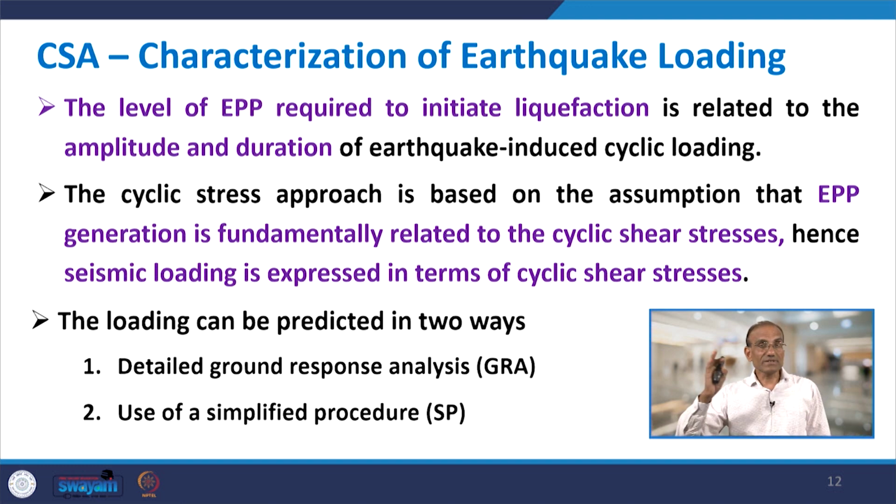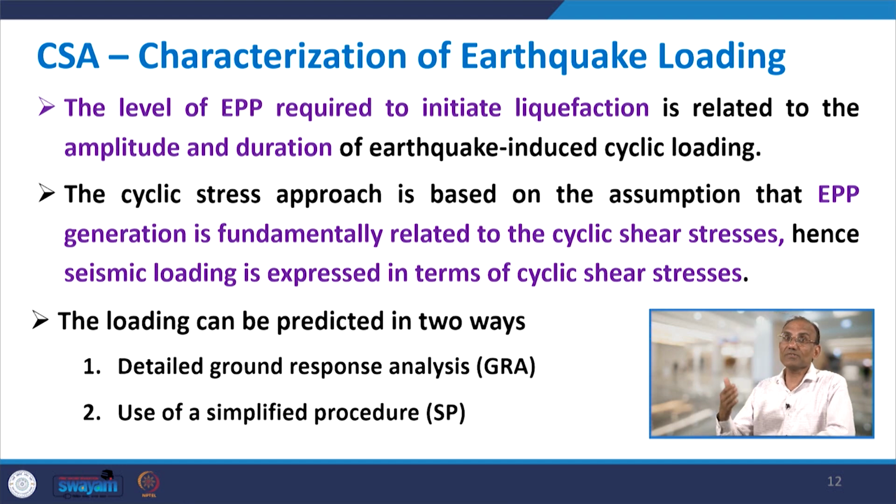Here, on one side we are saying, who is responsible for liquefaction? It is the increase in pore water pressure. So, when you induce the loading inside, it will create excess pore pressure, and we are linking that with the generation of cyclic shear stresses. The loading due to the seismic load, in terms of cyclic shear stress, can be predicted by using two methods. One is detailed ground response analysis, which is called GRA in short, and another is what we call a simplified procedure.